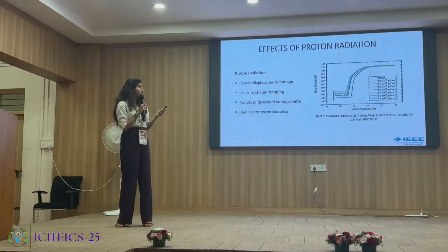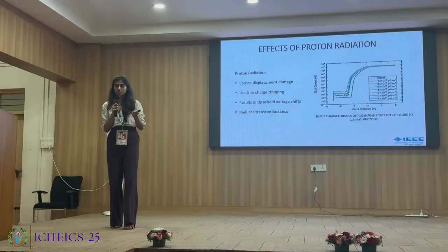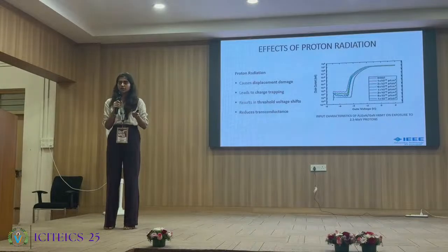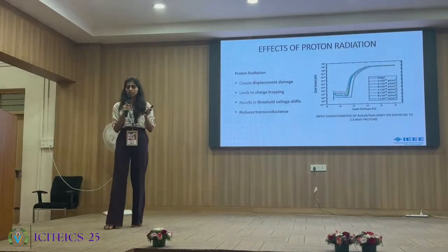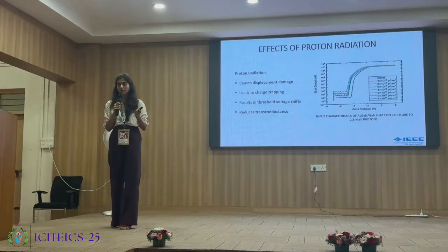Additionally, damage from the proton is also associated with the type of substrate that has been used in the device. For example, the gallium nitride HEMT with the sapphire substrate tends to show more resilience compared to the substrate with silicon carbide.